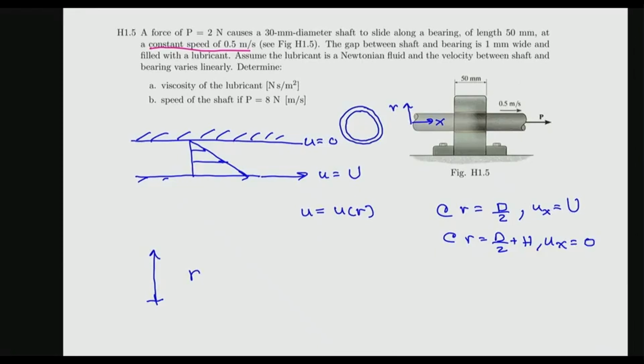And then in cylindrical coordinates, tau, and it would be rx, so the first subscript indicates the area. So the shear stress acts on, so the area normal is in the r direction. So the surface that the shear stress acts on truly is cylindrical, right? It's this cylinder.